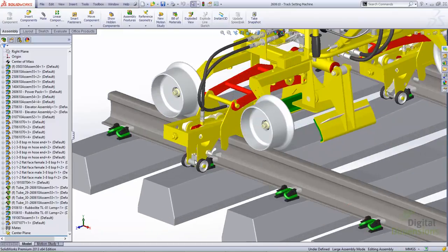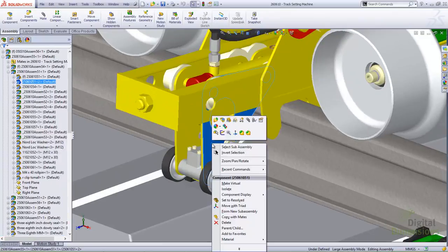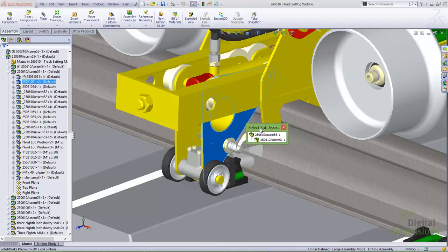Well, now in the latest version of the software, whenever you right click a file and you say select subassembly, you're going to get a list. You'll see here, it's going to show you each of the subassemblies that that part belongs to. And if I had 3 or 4, you'd see 3 or 4 listed there, so it's an easy way for me to select which one I'm actually referring to. In previous versions, it just defaulted to the next level up. But now you're going to get this box allowing you to choose which one you'd like.